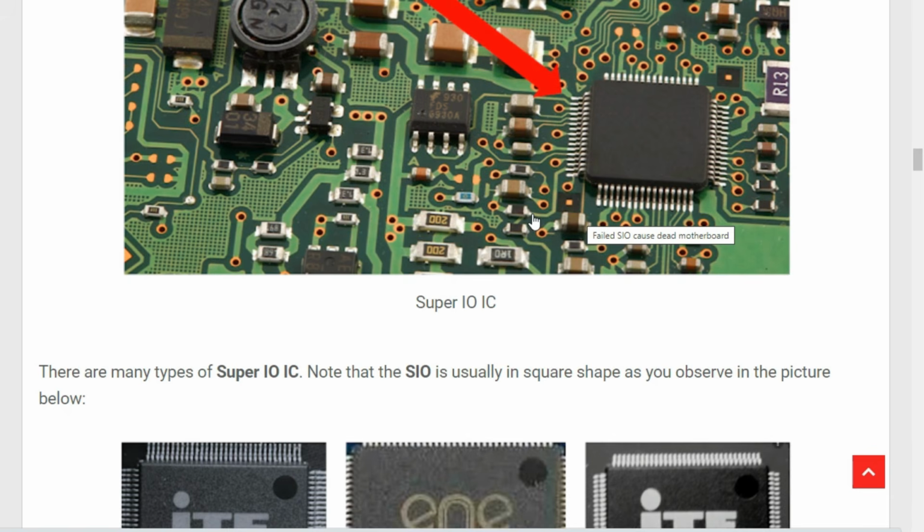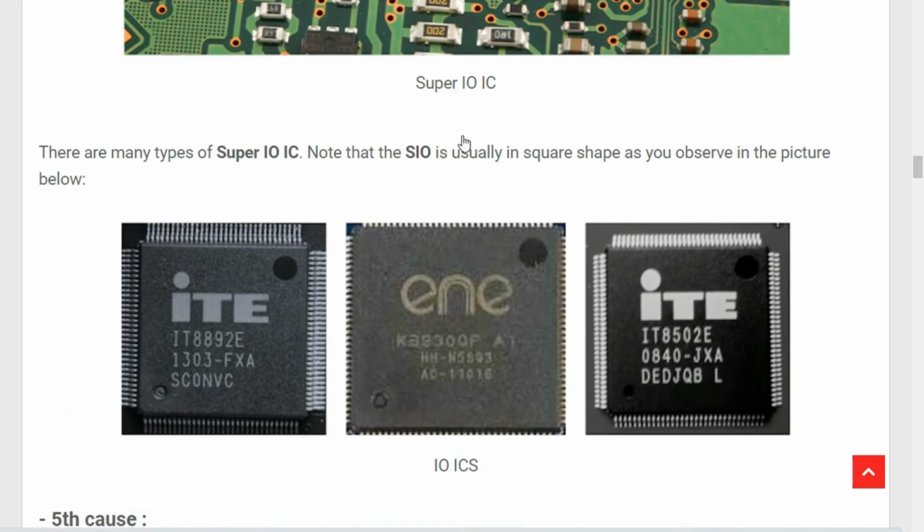Check, for example, VIN. Do you get 19 volt in VIN? You should check the enable signal, 3 volt. All inputs and outputs of the IC. But this third method is not easy. So you can just use the first method to check the heat of the IC, and the second method, the ceramic capacitors around the IC.